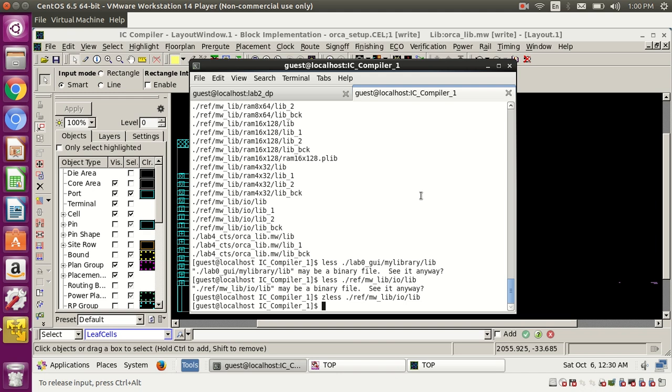And because the clock is a high frequency signal, it has to switch every time, and it will consume that power. Suppose in the data path we have an AND gate, it may switch once in a clock cycle, or twice, or for 100 clock cycles it may not switch, because the inputs may remain the same.